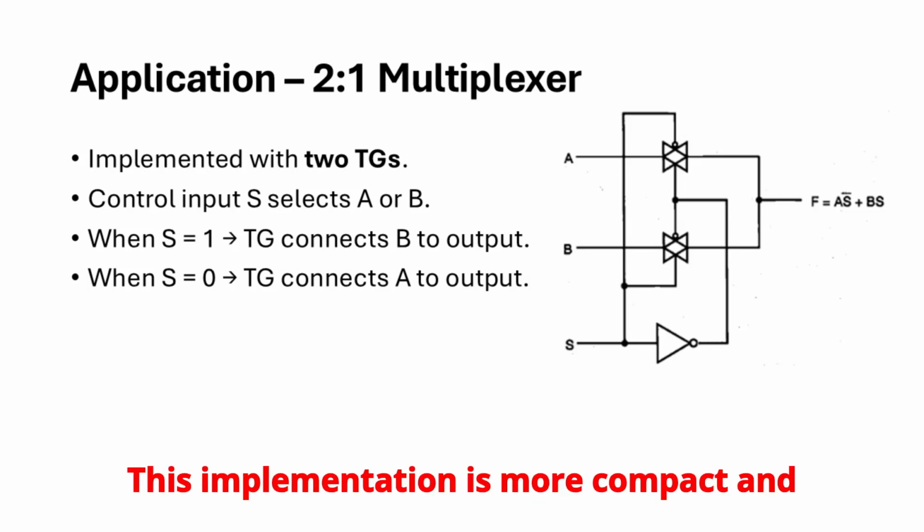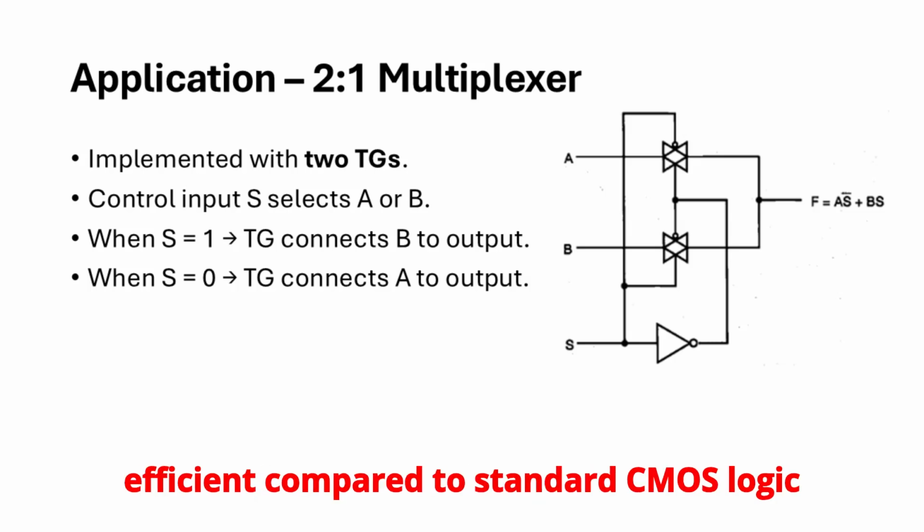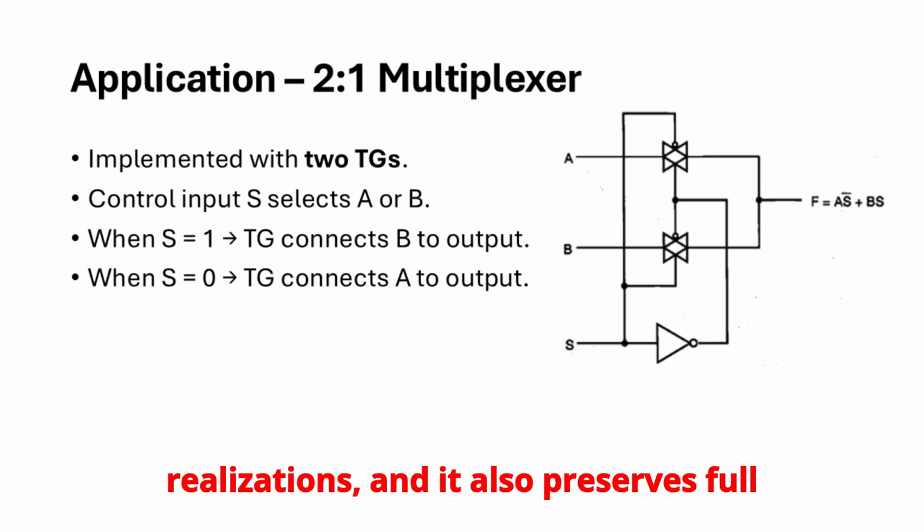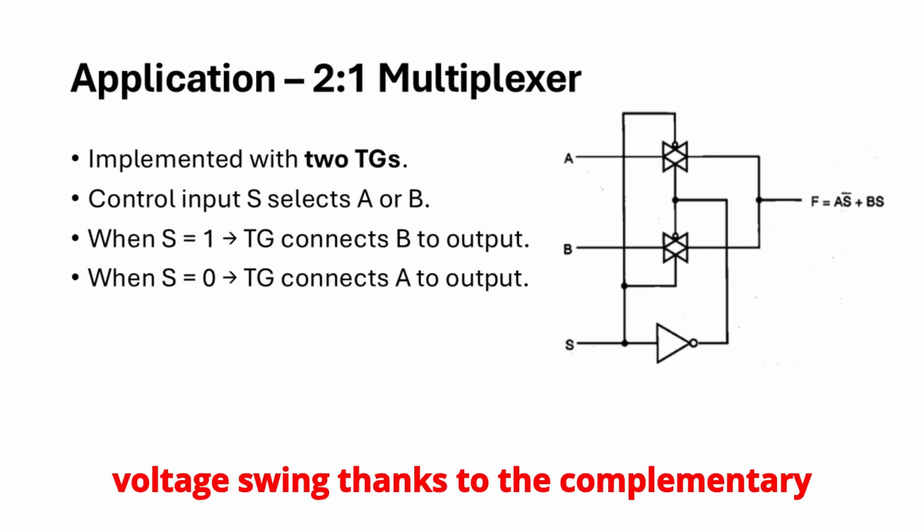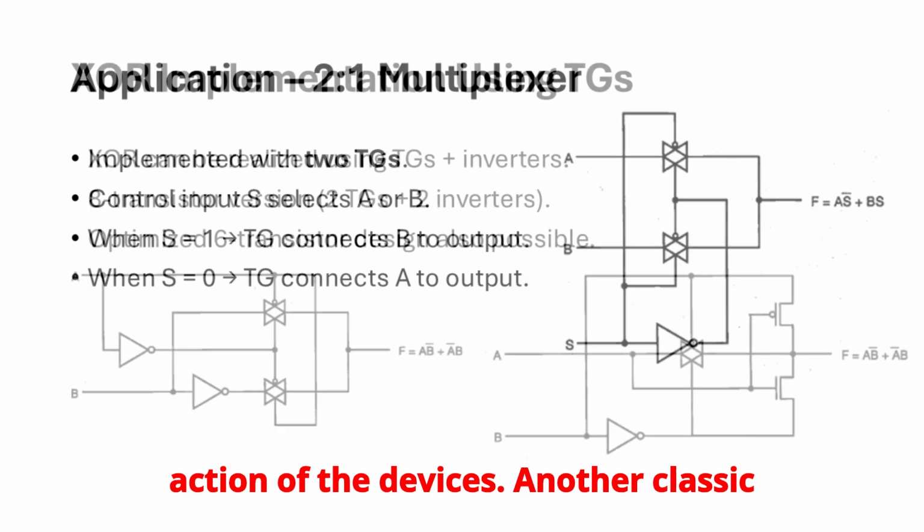This implementation is more compact and efficient compared to standard CMOS logic realizations, and it also preserves full voltage swing thanks to the complementary action of the devices.